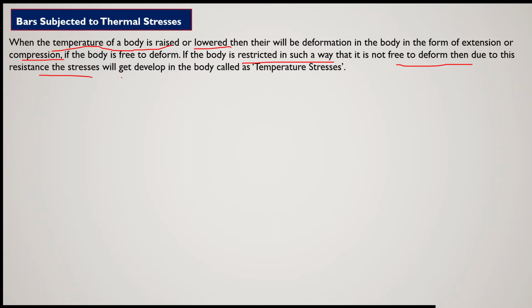The supports will be resisting any type of extension or compression. So some stresses will be developed, and those stresses are known as temperature stresses, because the reason for development of those stresses is the change in temperature of the body.